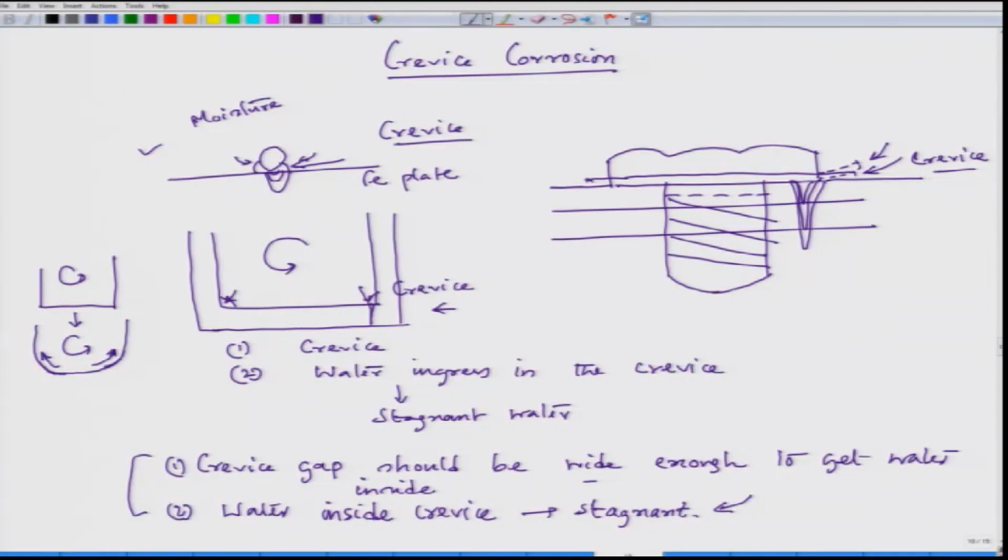corrosion. And in this case, for example, we first have to try that there should not be any crevice. So, one way is we can chop off these particular edges, which will allow this gasket not to protrude out, so that the crevice is avoided. So, this is the design factor we can think of. Now, this crevice corrosion itself is a wide subject. So, we are just giving a nutshell of what the form of crevice corrosion is.